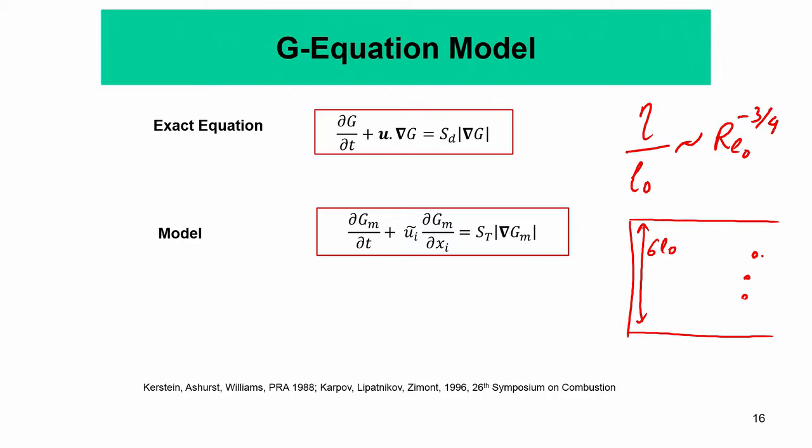So, even if you have this exact equation for the propagation rate of the flame surface, which is governed by say G, even if we assume that this G equation can describe the propagation of the flame surface exactly, that requires a very good model for U and that you can account for density variation somehow in the flow field. Given that you have a turbulent flame, this turbulent flame will be wrinkled at a multitude of length scales, right.